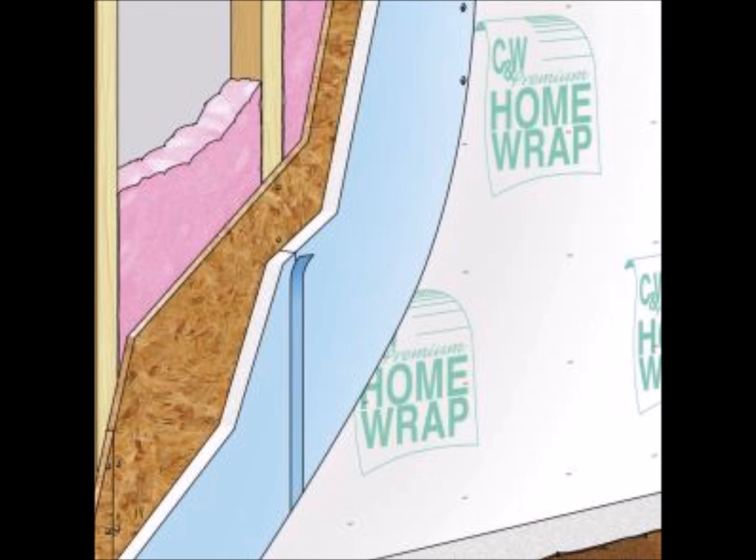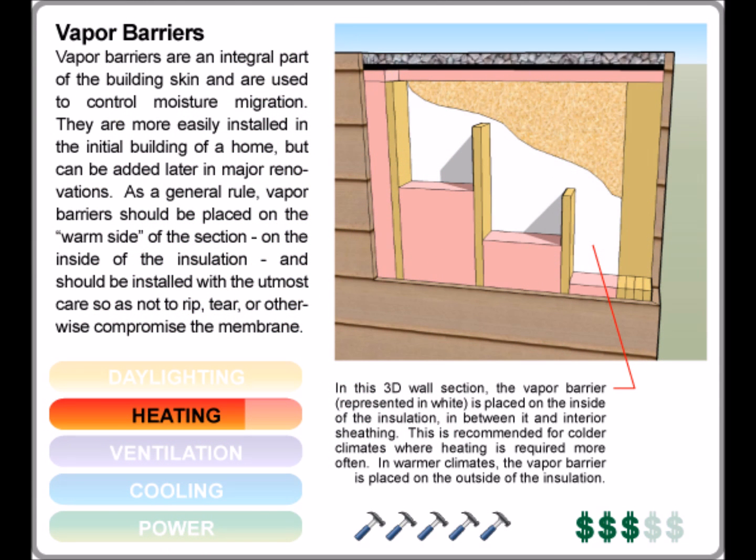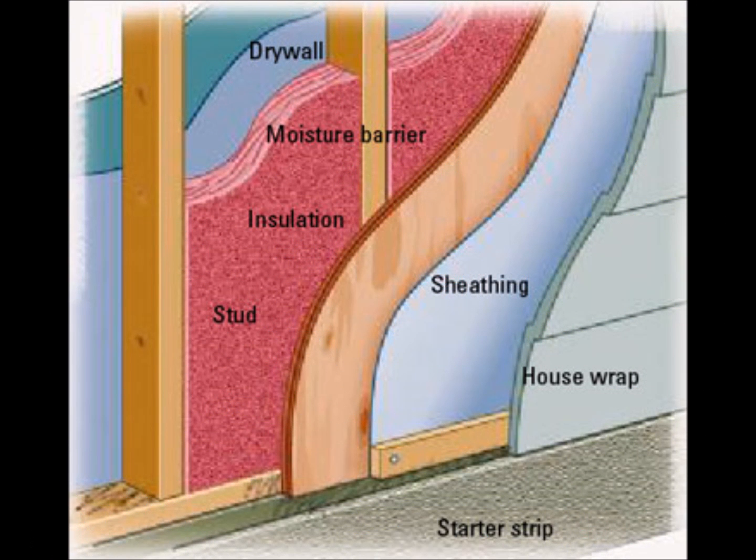Hot and humid climates: install air and vapor barriers on the exterior building walls. We want to make it as difficult as possible for building materials to get wet from the exterior. We want to let the building materials dry to the interior. And finally, interior spaces must be maintained at a slight positive pressure with dehumidification. Interior spaces must be kept below 50% humidity. In hot and humid climates, this requires both dehumidification and the use of ventilation to create a positive pressure within the conditioned space so as to prevent infiltration of humid outside air.